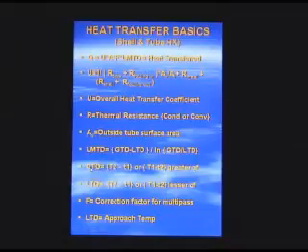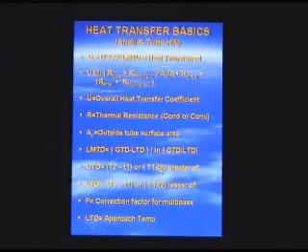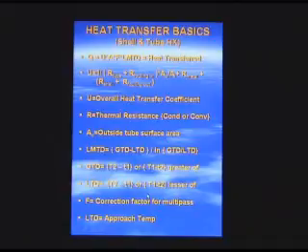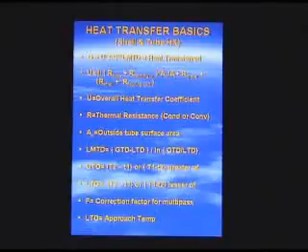Again, the greater temperature difference would be, T2 would be the shell side outlet, T1 is the shell side inlet, or conversely you can have the shell side inlet or the tube side outlet. Depending on how that falls out, that gives you the greater and lesser temperature differences. The lesser temperature difference, okay, anyway, we've already covered that.